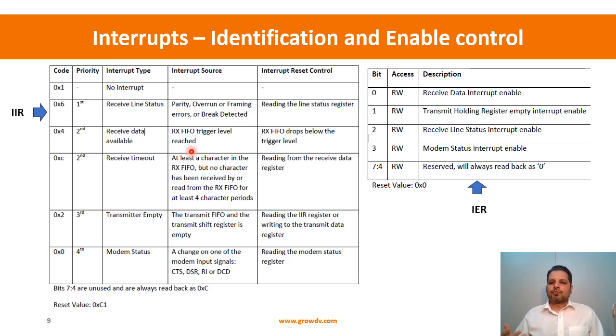If it is very quick, you can keep a lower threshold so that the processor can do more work, right? Or depending on the line speed, so that depends on the application condition, how you configure, but it allows you to configure. So next time it will be able to see this, and then what it means is the processor has to keep reading a few entries, and when the number of entries in the RX FIFO drops below the threshold that you had configured because of the processor reading them, then this particular interrupt will get cleared, right?